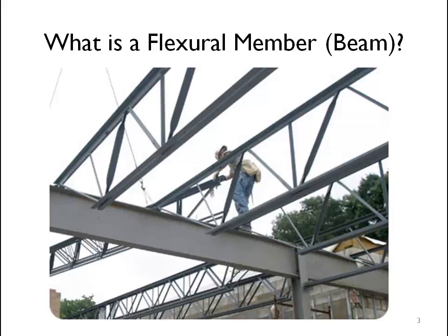This photograph includes both. You see that we have a rolled shape being used as a beam or a girder in this direction, and then in the opposite direction we have open web joists also being used as a flexural member. Now, maybe you already have discussed joists in lab at this point, and we're going to leave our discussion of open web joists for the lab.